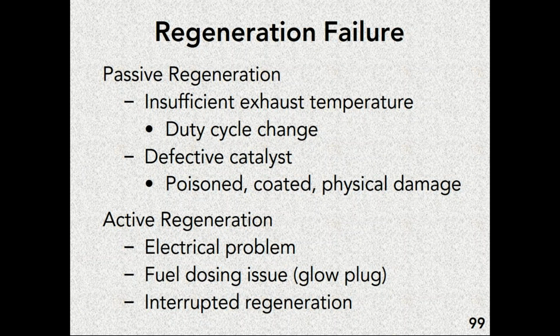It could be that you have a defective catalyst. Maybe you got a tank of gas that has too much sulfur in it and you just poisoned the catalyst. I've seen that happen three times with people who went south of the border and picked up some fuel from Mexico, where even though they do have sulfur content limitations, they don't monitor as closely as we do. So it's entirely possible to purchase high sulfur diesel across the border.